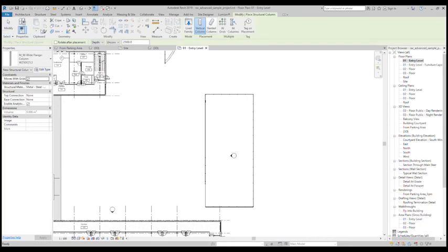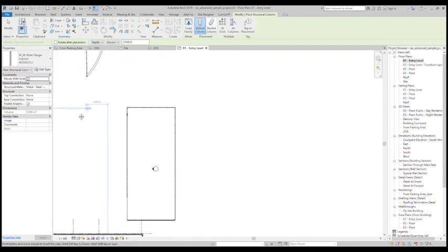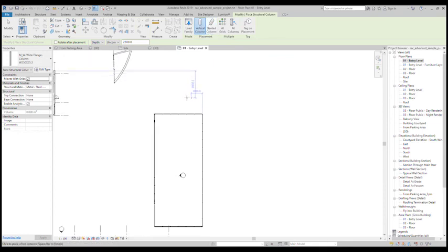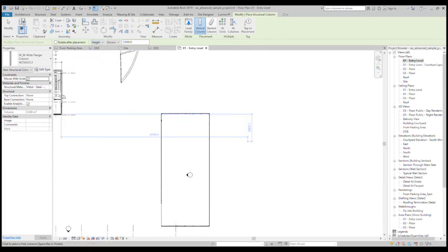Once you click on that, you will get this window, and it's telling you, okay, what type of column do we want to place. I'm fine with regular I-beams just now, or I-columns, I-sections. And I'm fine with vertical columns just now. We'll look at slanted columns next. Before you place them, you have to tell Revit if you want the column to be placed from this level going downward, which is depth, or from this level going upwards, which is height. I always do height. I want to place my columns on the level that I'm looking at, going up.